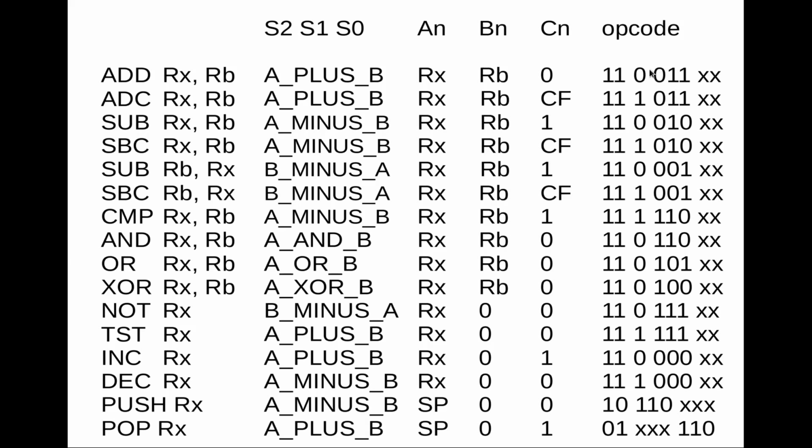that left us really with 4 bits to encode the operation, and then 1 set of 2 bits to encode some register, and so we decided that meant the second register in fact always had to be the B register, or we had simple single operand instructions. And then the first register would necessarily be one of the general purpose registers, A, B, C, or D, and so we couldn't use the program counter or the stack pointer as an input to any of these ALU operations. But then, in fact, we never actually defined the 4-bit opcode which we would assign to each of those instructions.